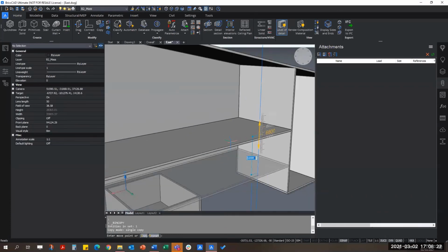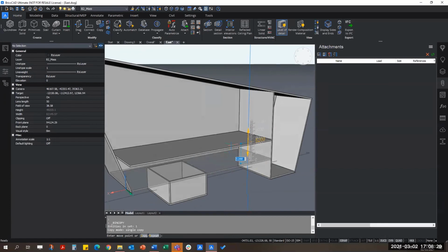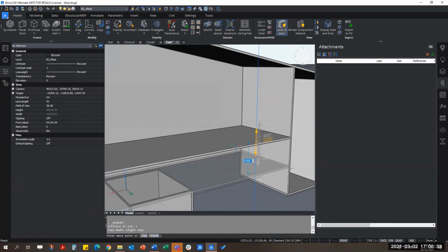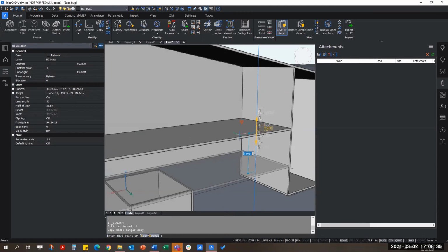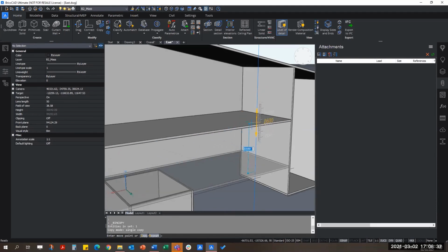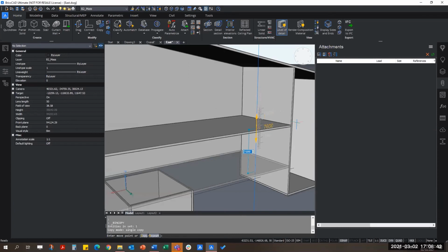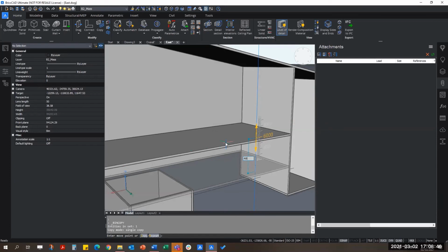So what it does is it's selecting the entire solid, not just the face, the entire solid, and a little bit like the manipulator tool, where you can select where you like to have it copied. And over in our case, I think we can do a 4 meter floor-to-floor height.